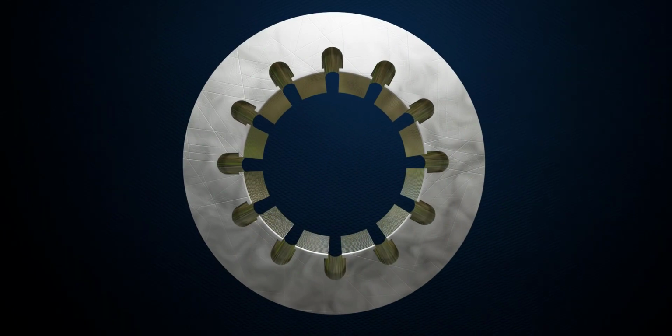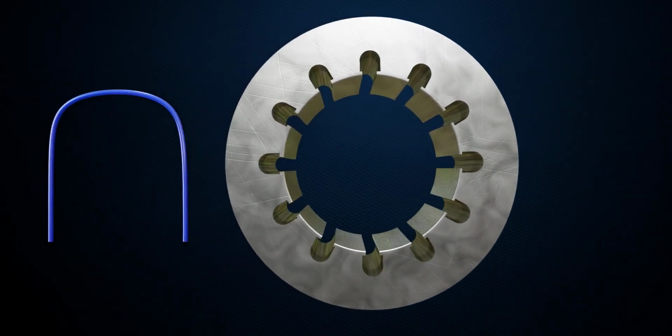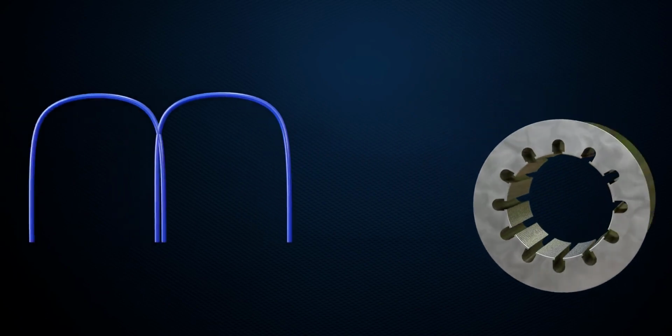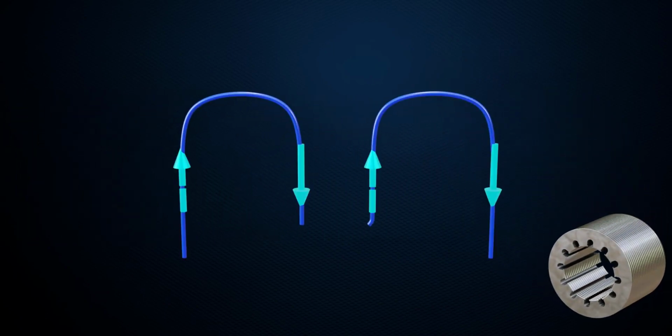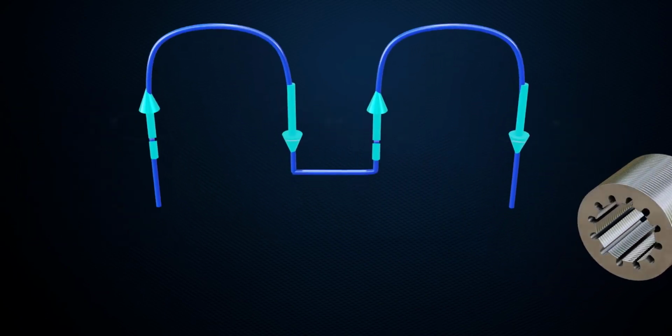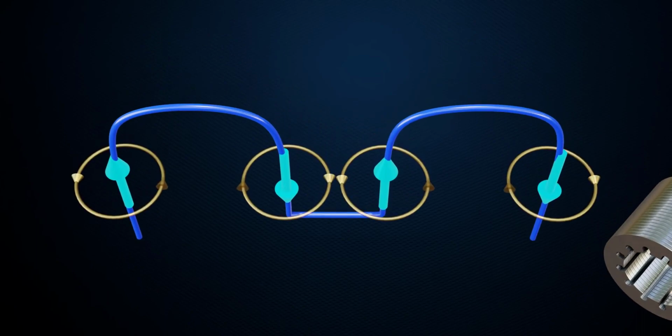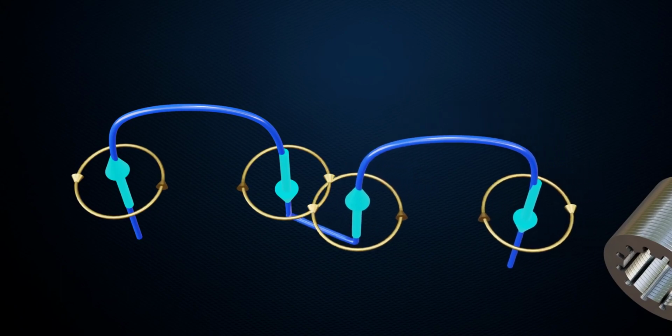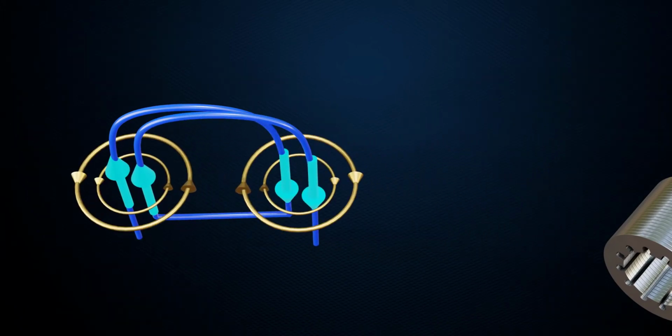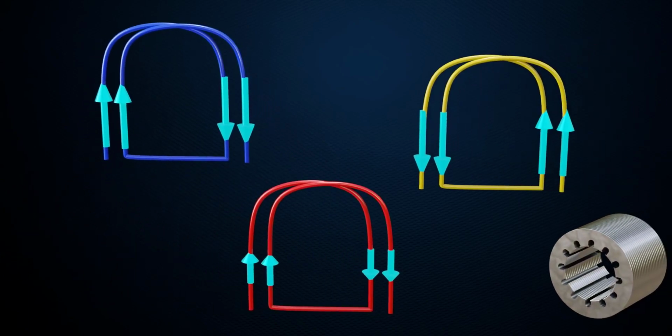The winding of this 12-slot design is made by connecting one more coil in series with each phase coil. Here, observe the current direction. Well, this straightforward connection won't produce a two-pole magnetic field. Let's overlap this pair of coils. What you get is a two-pole field. Perfect. Now, let's do the same for the other two phases.